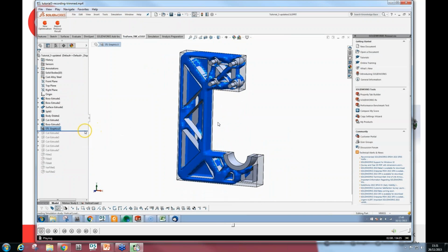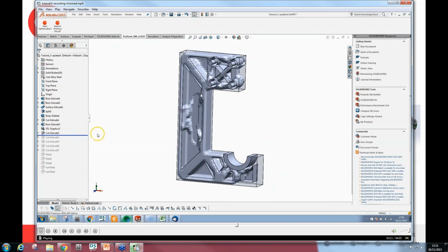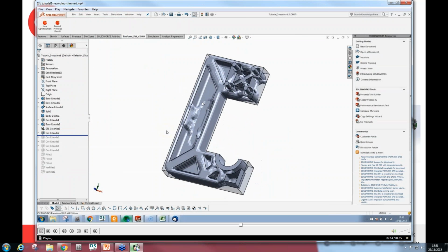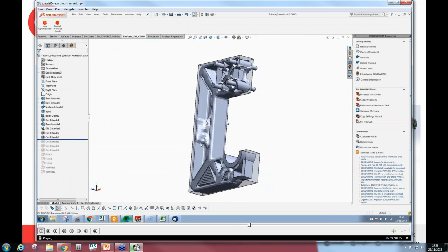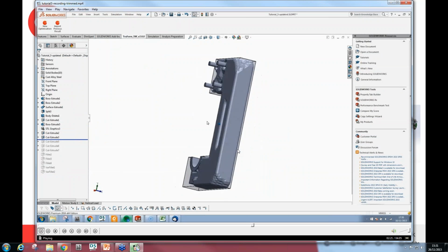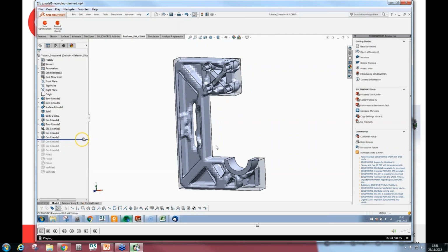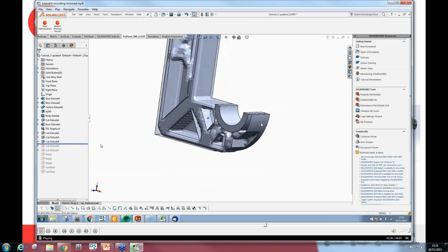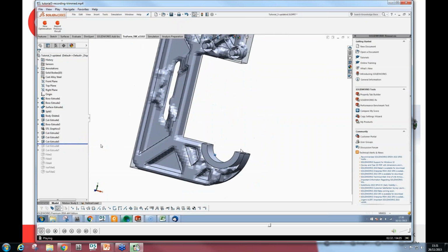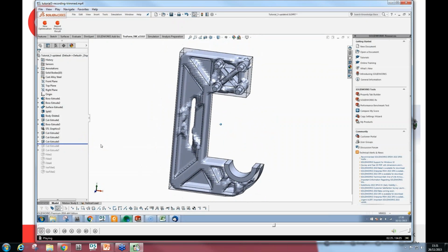Okay, so now what we'll do is we'll work our way through the various design updates to remove the material to follow the suggestions of TruForm. So we'll start off by removing the two ribs from that central section, that main load path section that's not doing much work. Then we'll introduce a cut hole through the surface. And as the next step then, we'll trim away the loaded region and remove that excess material that is applied.